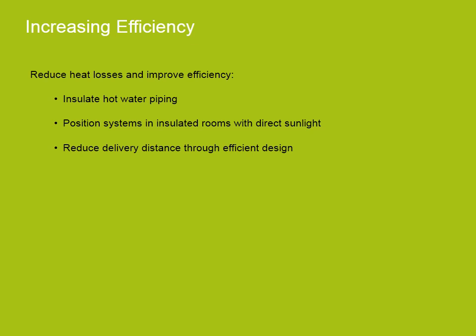To reduce heat losses and therefore improve efficiency, you can insulate hot water piping, position hot water systems in insulated rooms or in areas that receive direct sunlight, therefore increasing the ambient air temperature, or reduce delivery distance from heat source to destination through efficient piping design.